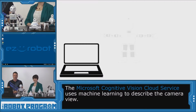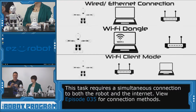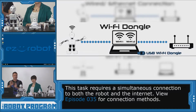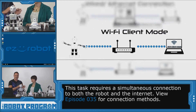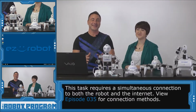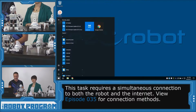So to do that, you're going to need your computer to connect to the internet and your robot at the same time. Now, there's three ways to do that. One way is to have two Wi-Fi adapters. You can add an additional Wi-Fi adapter using USB to your laptop, or you can connect your laptop to Ethernet, or you can have your robot connect to the router, and your laptop can also connect to the router, and they can both see the internet at the same time. In this case, we're going to use two Wi-Fi adapters to connect to the router and the robot at the same time. To begin, we're going to load Easy Builder.